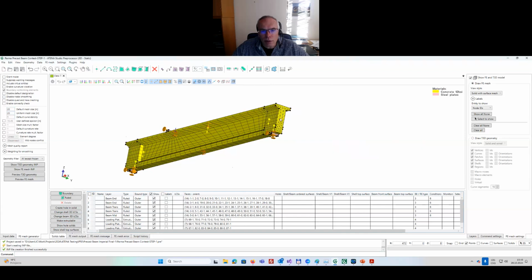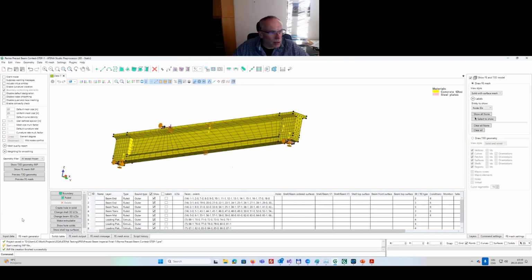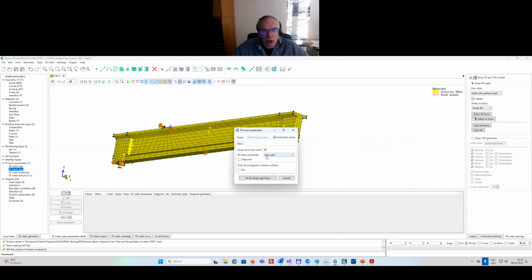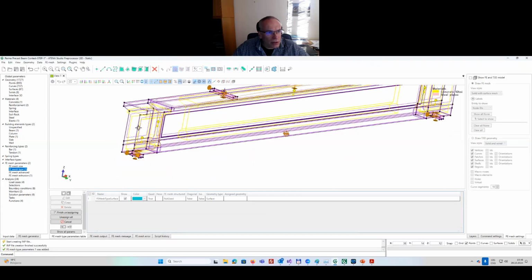I would like to have quadratic elements, or basically brick elements, not these wedge elements. So no triangles here on the sides of our model. In addition, so this is one thing that we need to modify. And in order to do that, we need to specify on the surfaces that we want to have a mesh type, which will be quad dominant. So let me go now and define to these surfaces of our